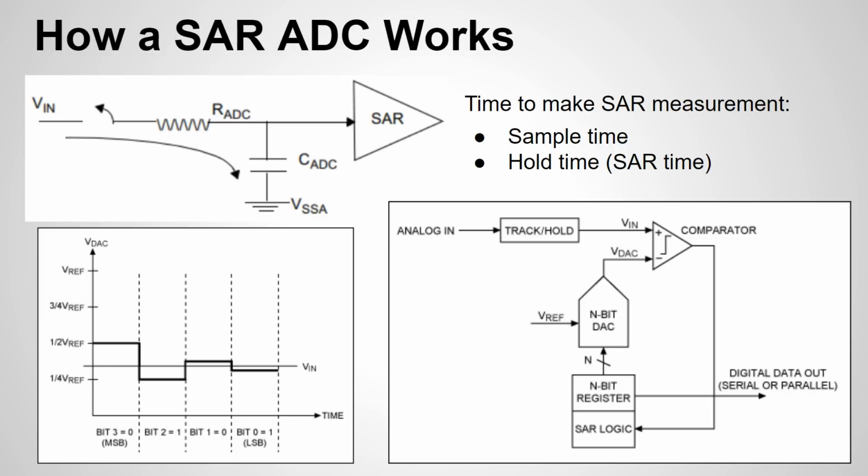But you can obviously probably imagine that when designing these ADCs inside the microcontroller, there's trade-offs if you make the resistance too low or the capacitance too low versus high. But it's important to note that the sampling time is dependent on these two values. It is also dependent on any impedance or resistance on the input signal, but we'll talk about that later.